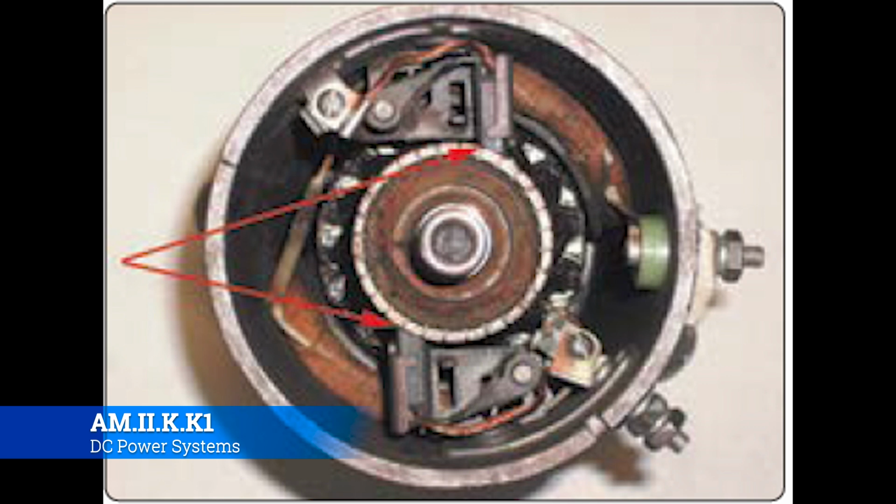Like I said earlier, the brushes are effectively like little brake pads, and so they're going to produce brake dust. And so you'll see that kind of fine brake dust all throughout the generator. It's not that big of a deal, but what you don't want is for it to start to pile up in one area and start blocking airflow. So if you're taking these apart and you have access to shop air, definitely blow them out. Get all that dirt and grit and grime out, and then just pay attention to the component maintenance manual and the aircraft maintenance manual, because it will tell you other little areas